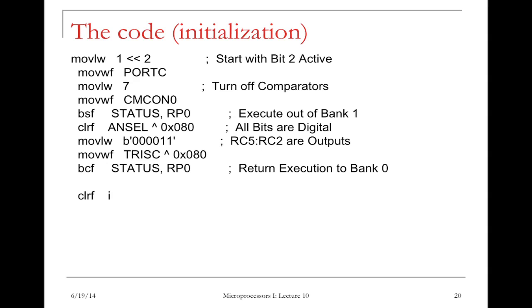Because you could use these pins as analog signals. But what we want to do here is digital. It's either 0 volt or 5 volt. That's digital. For analog, you're talking about could be from 0 to 5 volts in the whole range. But for our control sequence, we just want it to be either 0 volt or 5 volts. Okay? So that's the purpose of this instruction.